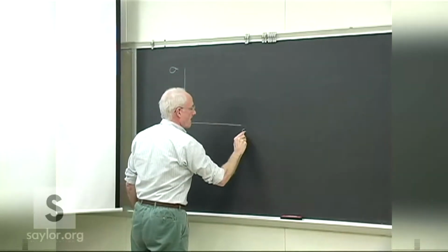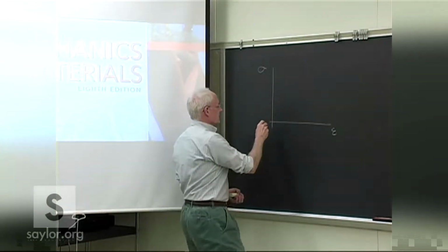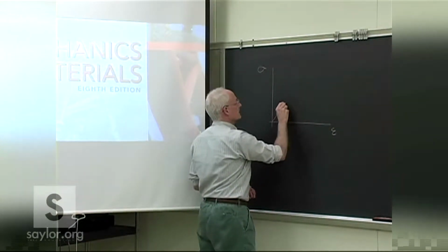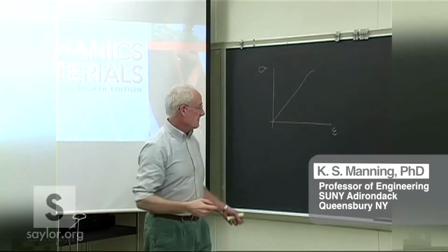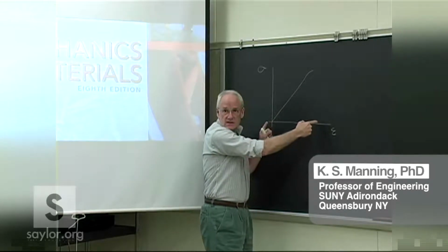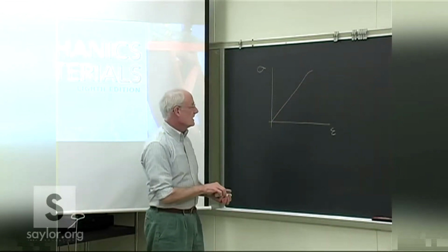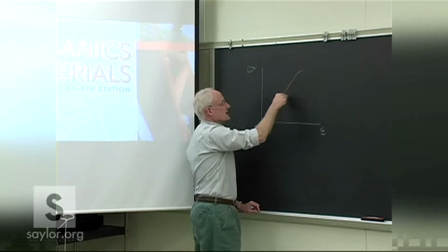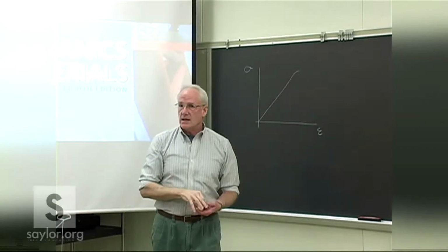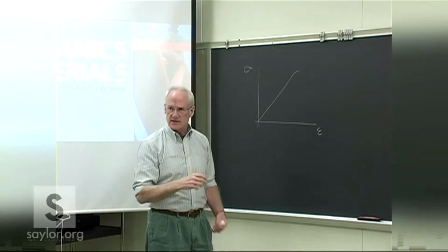Stress-strain diagram for different materials, and what was of particular interest to us was this very steep linear section. By very steep, I mean that these strain numbers on the x-axis are very, very small. We're still not in a large deformation zone, but the best part about this is, of course, that this is linear, and it's retraceable. There's not what we call hysteresis.